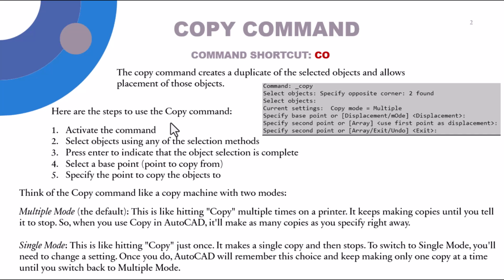There are two modes for this command. The multiple mode, which is the default one, allows you to place as many copies as you want, and there is a single mode where you're going to copy the object only once.